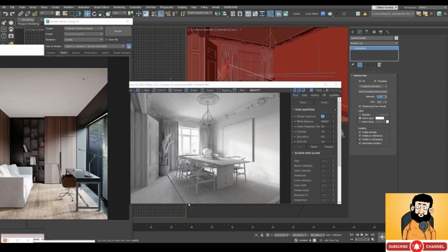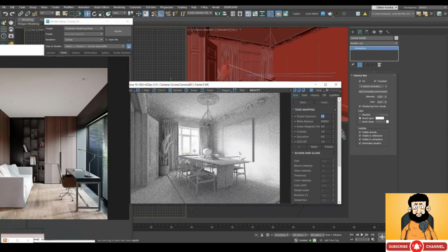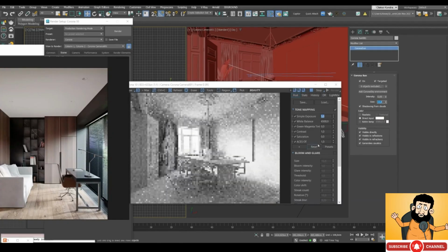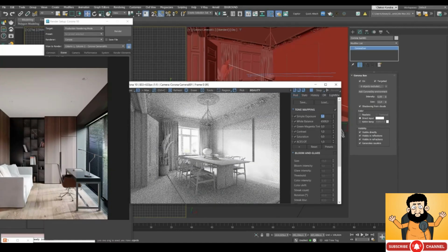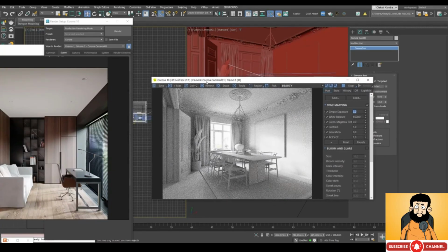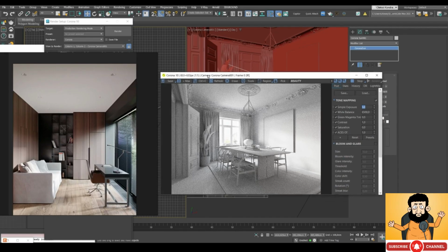The only difference is that the floor in our scene is not sunlit because of the table here. But the settings and the sunlight are pretty much similar. We can also double the size of the sun to make the picture even more similar to what we have in the reference. But in that case, the shadows from the furniture are missing. So I'll put a value of 12, and that's basically enough to keep the soft shadows. Basically that's it. That's the quickest lighting setup.